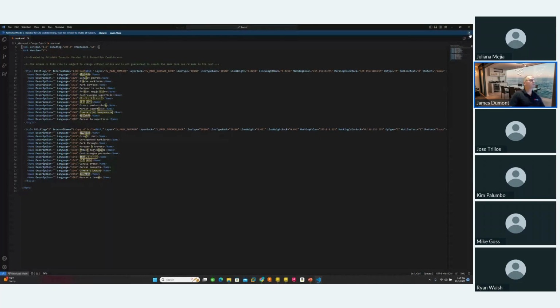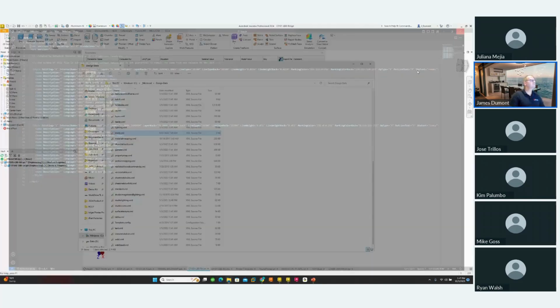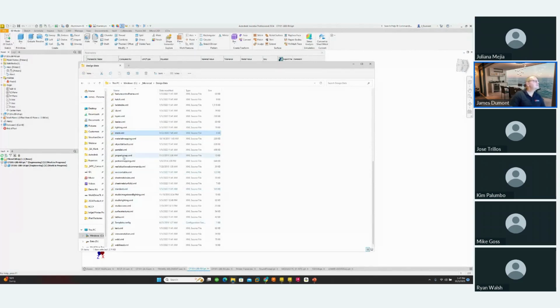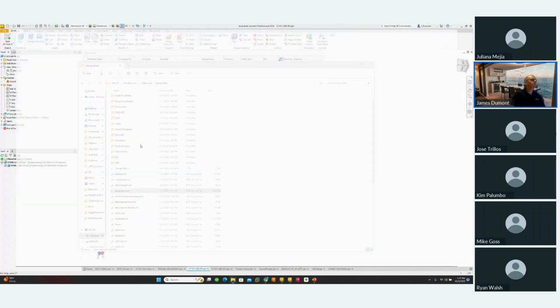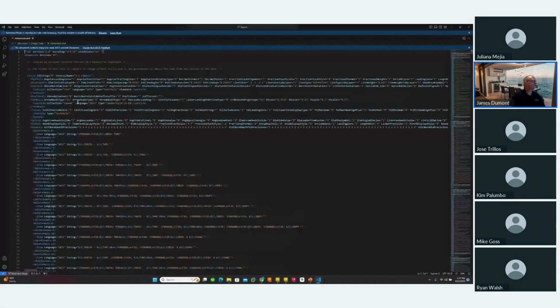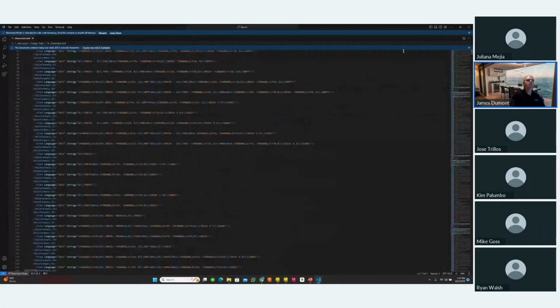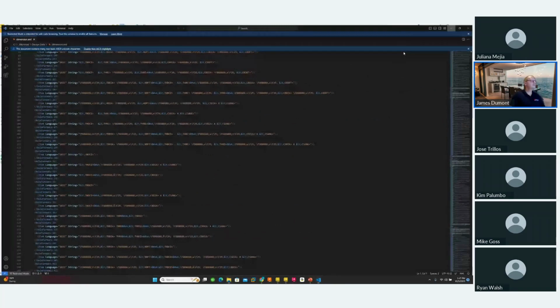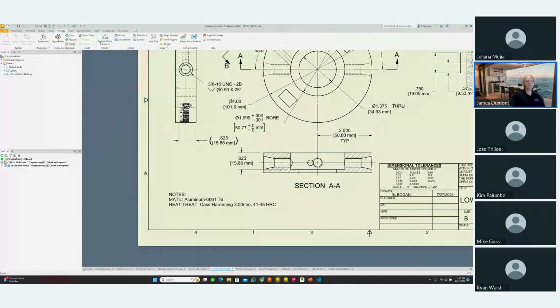So most of you, when I upgrade your systems, I'm always getting into the styles. I have to migrate it. And one of them that's in there is you're going to see balloons, dimensions. That's a biggie. These are all your dimension styles, the units. No one edits the styles like this. So if you're in a drawing file, you go to Manage, Styles Editor.